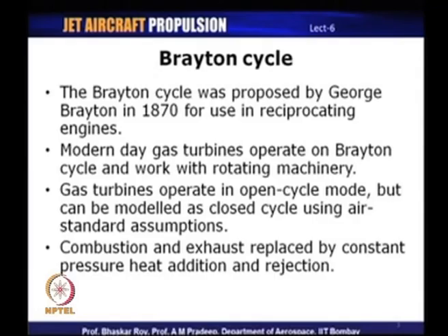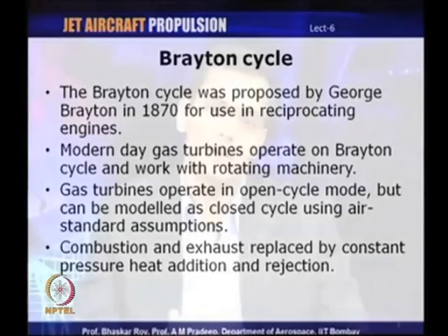In Brayton cycle analysis, we will see that the combustion process, which is what is there in an actual engine, as well as the exhaust process, is replaced by heat addition and heat rejection processes. We shall not be exactly modeling combustion or exhaust, but we will model them as heat addition and heat rejection processes, because thermodynamically that is much easier to analyze.